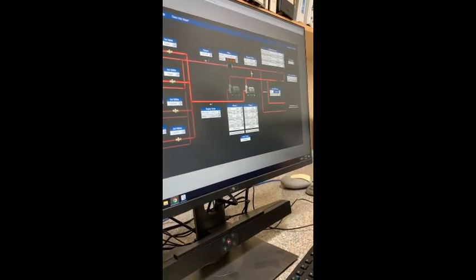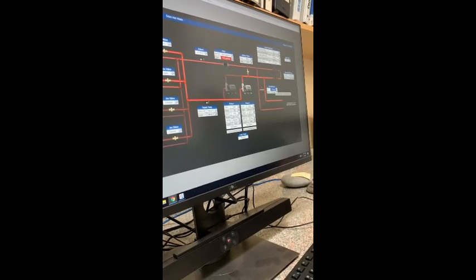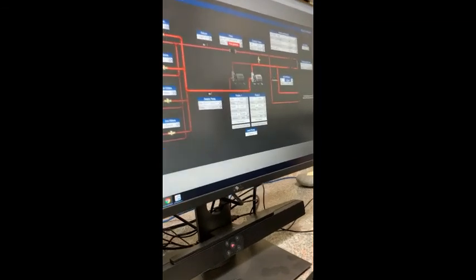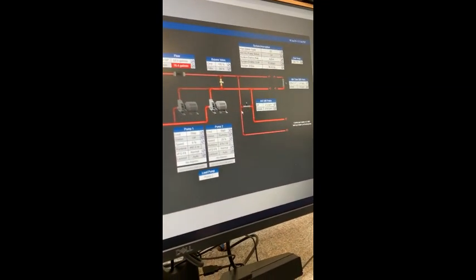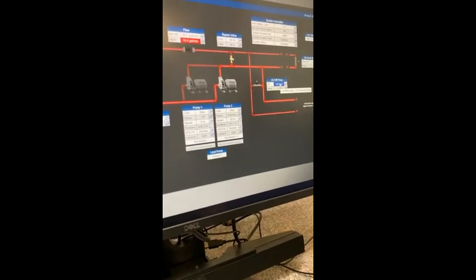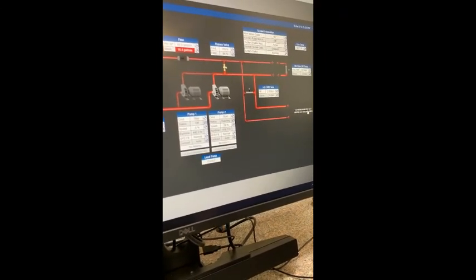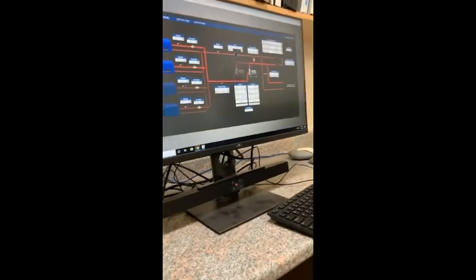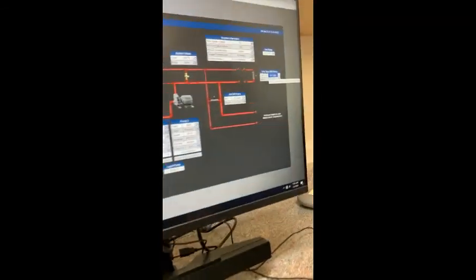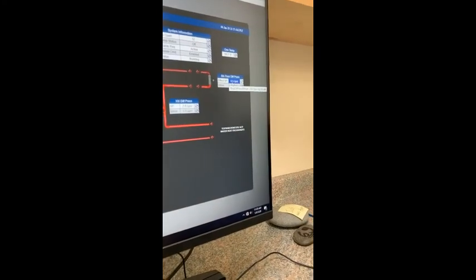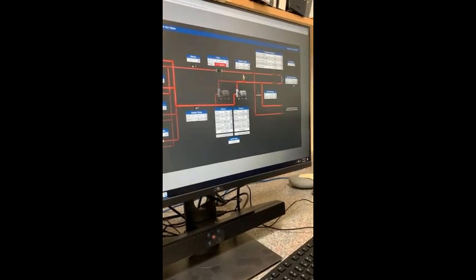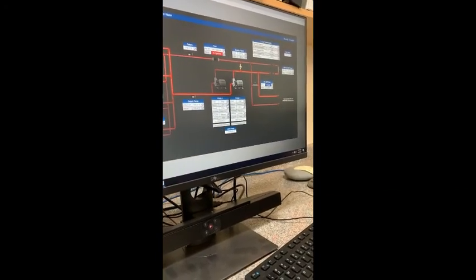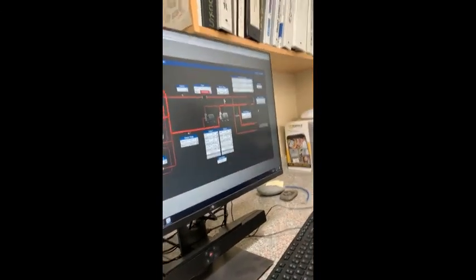So we have two things that will drive these pumps. It's whichever one has the most demand, either keeping the DP up at the differential pressure for the domestic hot water heat exchangers, or the 8th floor. We can see right now our effective set point for the 8th floor is 0.5, but we are over it, so that's not the driving force. The differential is keeping it right here. So whichever one needs the demand will be the driving one.